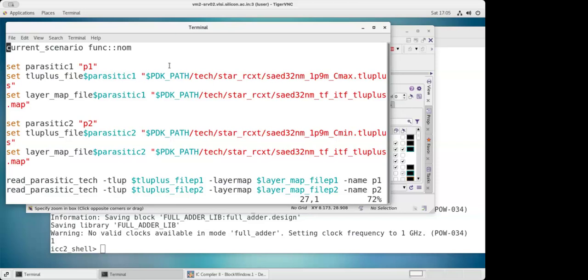So the foundry is telling, in which variation the capacitance is going to be the minimum, and in which dimension variation the capacitance is going to be the maximum. In that particular file, where W min was written as 2, maybe in Cmin, W min is going to be less than 2 or greater than 2, depending upon what kind of capacitance is going to be generated.